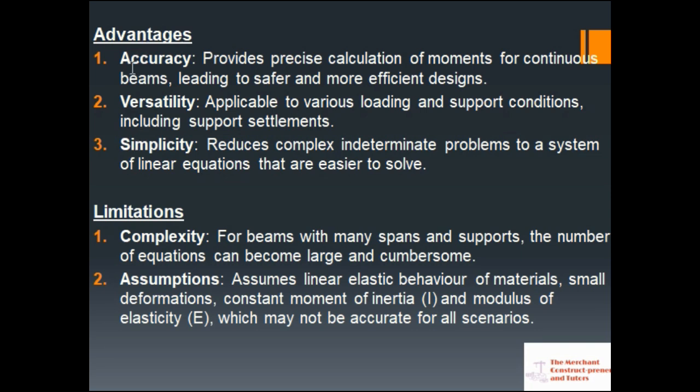For the advantages: accuracy. It provides precision in calculation of moments for continuous beams, leading to safer and more efficient designs. When you break this down to simultaneous equations, you are certain that it is no longer a cumbersome or complex calculation. Once you apply your simultaneous equations, just basic mathematics, you are good to go. Versatility: applicable to various loadings and support conditions, including support settlements.